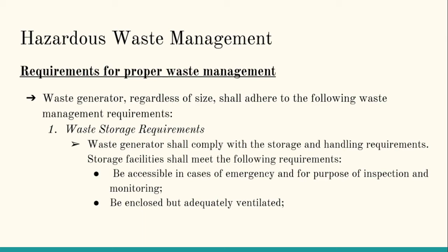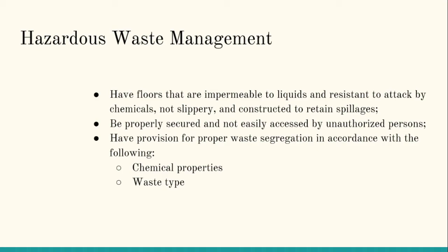Number 1. Waste storage requirements. Waste generator shall comply with the storage and handling requirements. Storage facilities shall meet the following requirements: be accessible in case of emergencies and for purpose of inspection and monitoring. Be enclosed but adequately ventilated. Have floors that are impermeable to liquids and resistant to attack by chemicals, not slippery, and constructed to retain spillages. Be properly secured and not easily accessed by unauthorized persons.